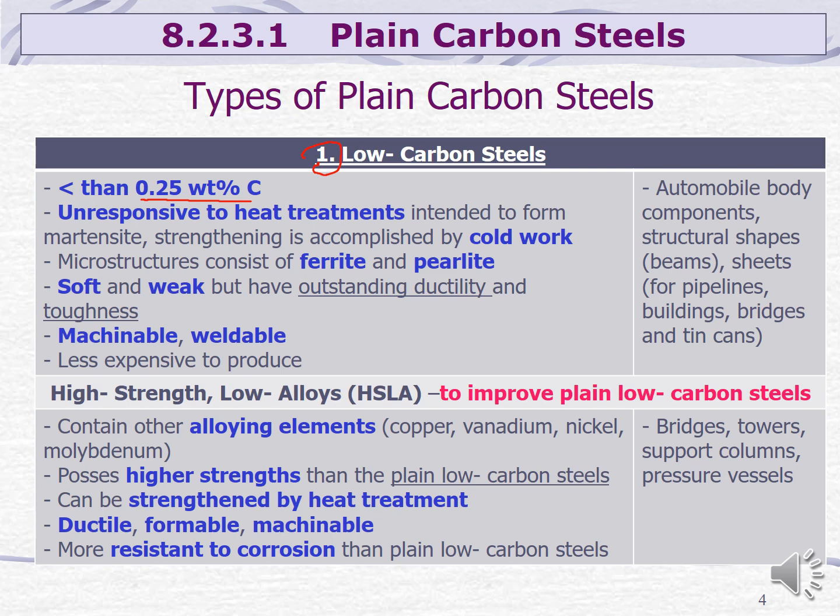This steel is unresponsive to any heat treatment process. So in order to strengthen the steel, we need to do a cold work process.